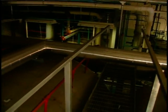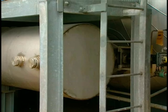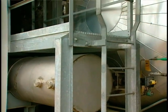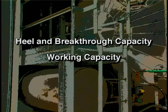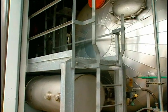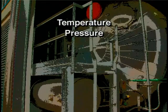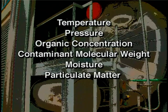To review, the common types of activated carbon adsorbers that capture air pollution regenerate on-site or off-site. Carbon adsorption systems have retention capacity that includes the heel and breakthrough capacity. Between these two points is the working capacity. The saturation capacity is the maximum amount of organic compounds the carbon bed can hold. Retention can be affected by temperature, pressure, organic concentration, contaminant molecular weight, moisture, and any particulate matter in the system.